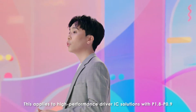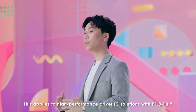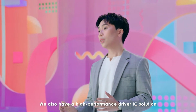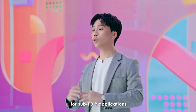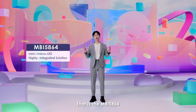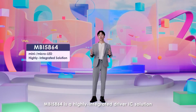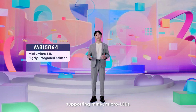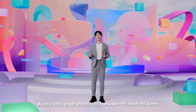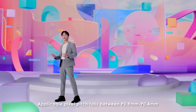This applies to high-performance driver IC solutions with P1.8 to P0.9. We also have a high-performance driver IC solution for sub-P0.9 applications. That is the MBI 5864. MBI 5864 is a highly integrated driver IC solution, supporting mini micro LEDs, applicable pixel pitch falls between P0.9mm to P0.4mm.